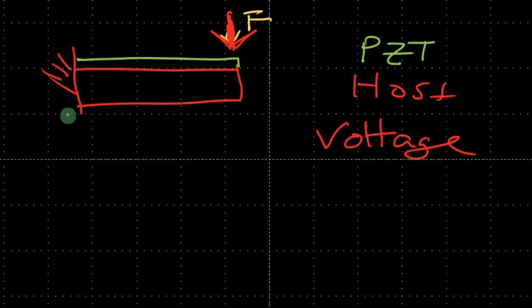And so let's talk more about this structure. The question we're answering is, what is the voltage here? The stress between these two, the piezo and the whole structure, are not the same. You'd think that this point is continuous right here. Rather, it's actually not continuous there. The stress is not continuous. However, the strain is continuous, and that's the key. So strain, I'm going to write as a curly X position. If I ever use it in this, I'll write as a regular X like that. So strain is the main thing we need to consider.